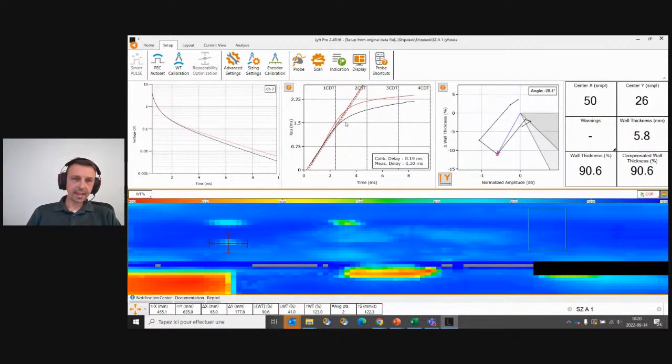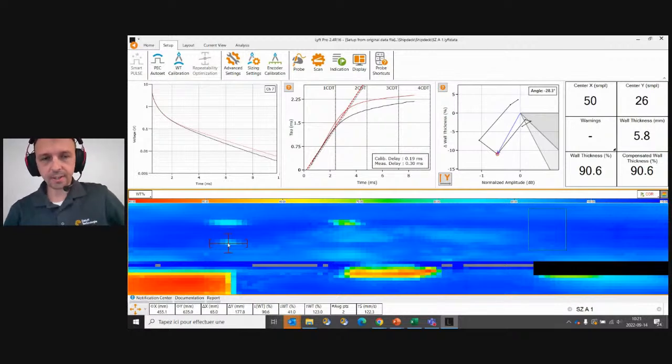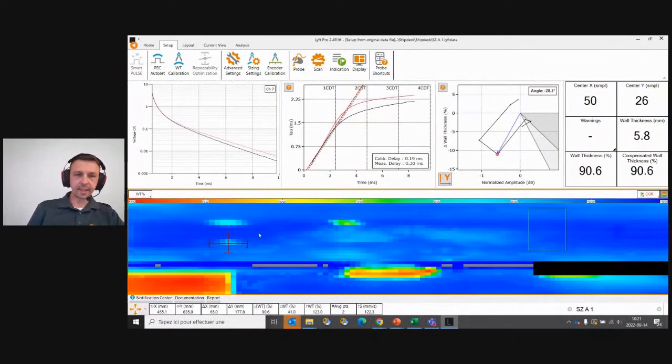If we look at the toe scan, it's almost parallel, but tends to try catching up with the calibration. And actually the size of this defect is close to the diameter of the averaging area. So we could use the computed wall thickness, but we must be careful in that case because we have the mass effect there and maybe some residual magnetization close.